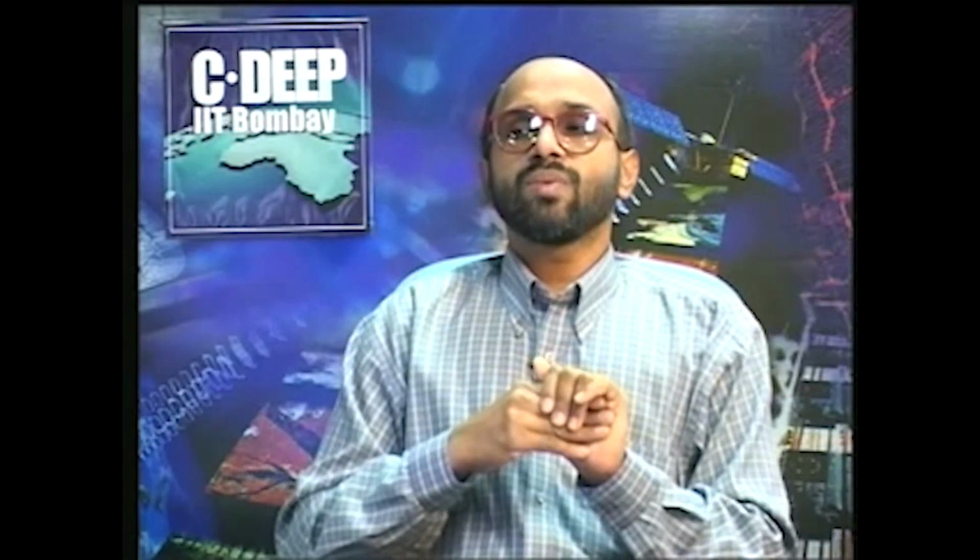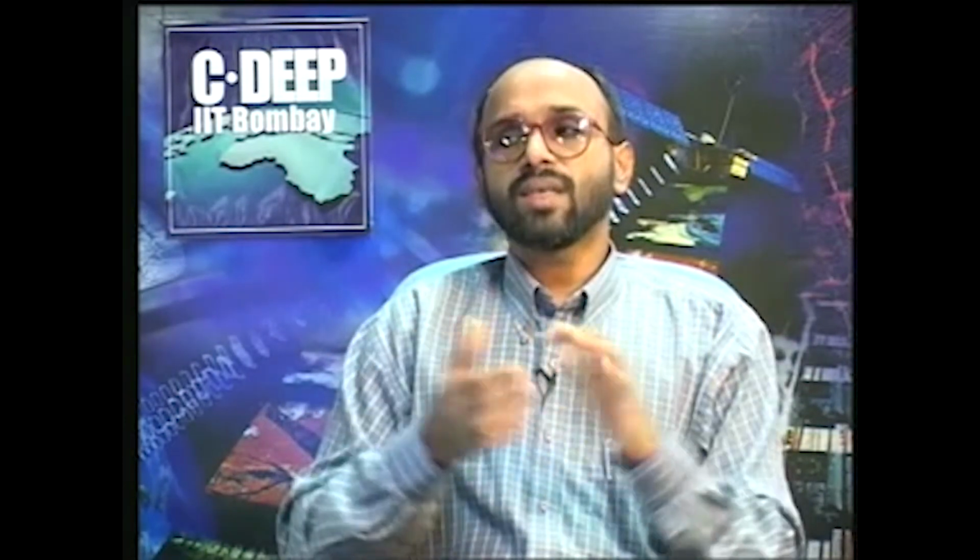Welcome back to the video course on fluid mechanics. In the last lecture we were discussing dimensional analysis, and we have seen the various laws like the Reynolds number law, Froude number, then various other dimensionless numbers, and then we were also discussing the various similarity or similitude theories. So, we have seen there are three fundamental similitudes or similarities which we have to observe while modeling.